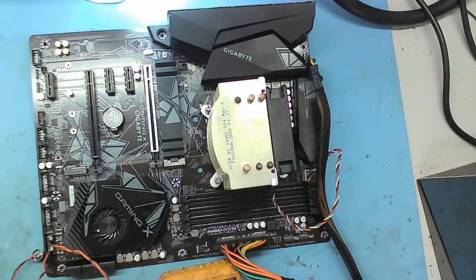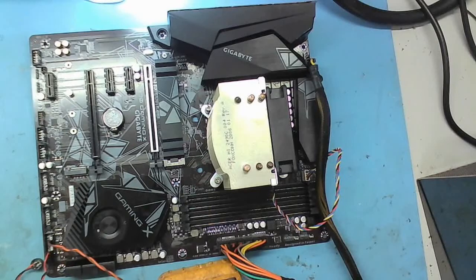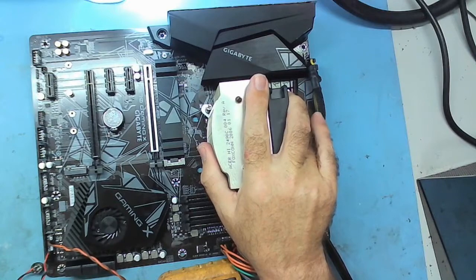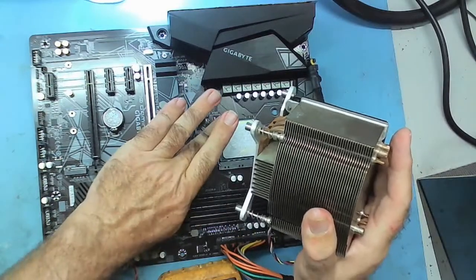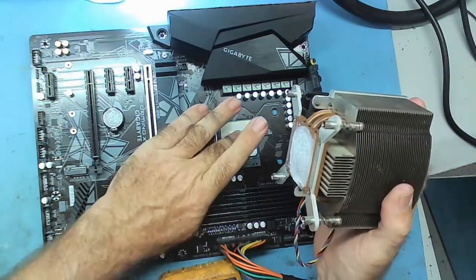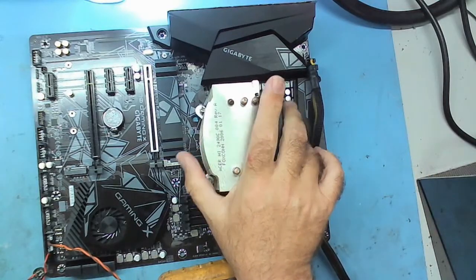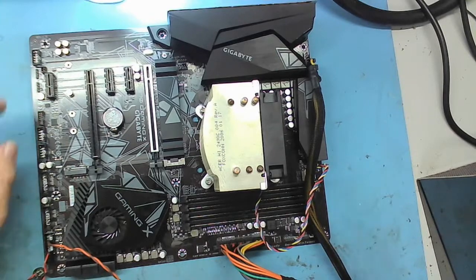Power supply on. Push the switch, and it powers up. No beeps. There's no RAM, so it should beep. No lights on this one. Maybe there aren't any lights. Oh, that seems to power up, but nothing else. The CPU doesn't really feel warm. The CPU feels cold. I'd have thought if it was running, the CPU would have a bit of warmth in it.